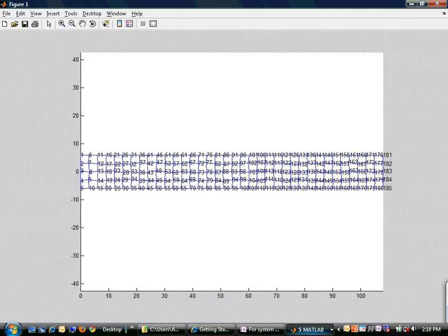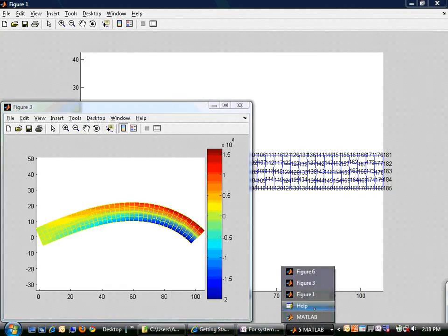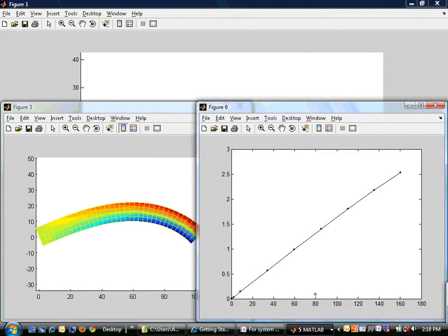So anyway, what this looks like is somewhat like this. You keep on applying the load here, and finally this beam turns around on itself, and you get this type of load deformation behavior, and ultimately you see that the load goes up and then comes down, and when the load comes down, all those points are unstable. What that means is it's still in equilibrium, but that equilibrium configuration is unstable, because the stiffness during all those steps is negative.